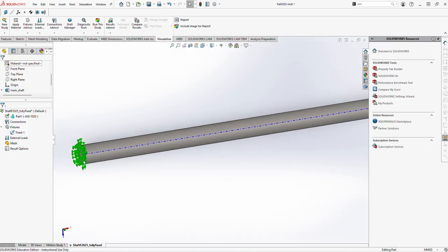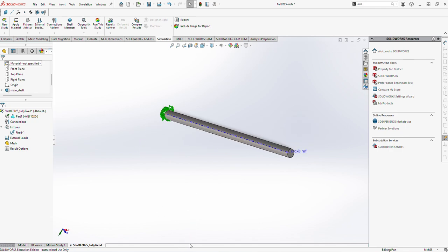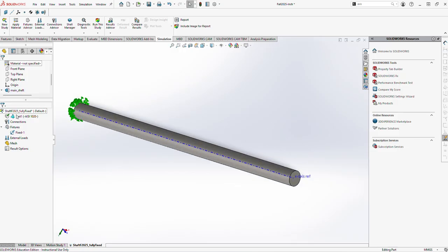But also remember that implicit in that formula that we have derived is the fact that this shaft is not acting like a cantilever. So this cannot bend downwards over here. So this shaft is going to remain perfectly straight. So we also need to apply that boundary condition on the shaft. So that is a kind of a bearing.